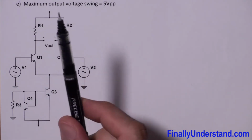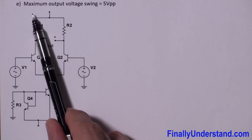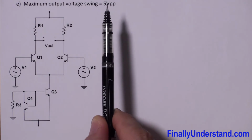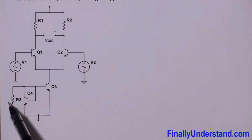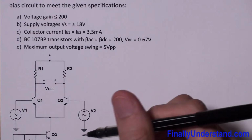And this time we're supposed to design the circuit which is going to have a maximum output voltage swing of 5 volts peak to peak. Okay, so where are you supposed to start? You're supposed to start from finding the value of resistor R3. Okay, so what are we supposed to do first?